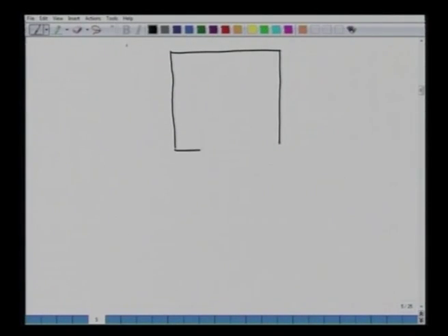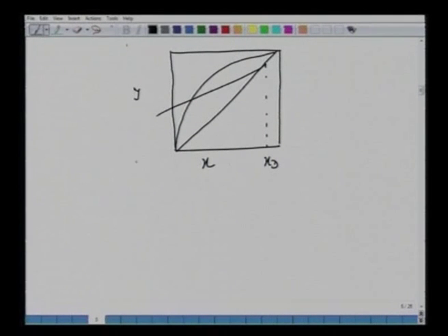So we have this y versus x diagram, and we have this 45-degree line. We have this equilibrium curve y versus x, and we start with xt as usual. We have a straight line for the operating curve with the slope, with the intercept, etc. Start from xw, you take another operating line here. Okay, now we want to mark this feed line, Q line.